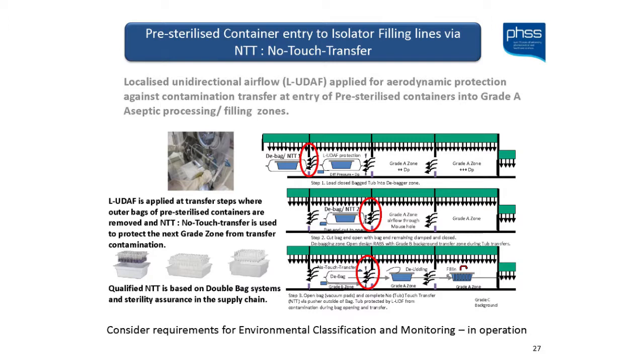We had to, in the industry, look for another solution. So importantly to understand that these technologies, I wouldn't put hydrogen peroxide anywhere near pre-sterilized containers. And I do know some of these rapid decon chambers have been put in 2 lines using pre-sterilized container transfers. Some companies have recommended that approach. And I do know 2 of them have been taken offline because of issues of residuals.